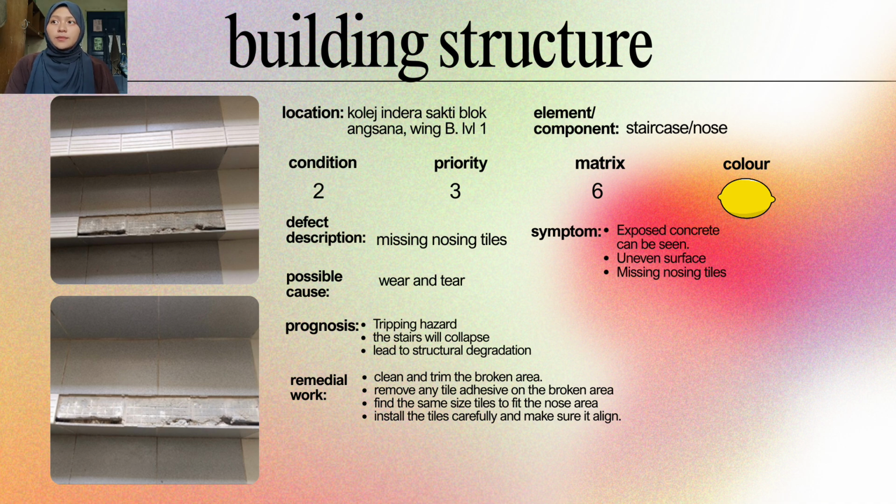Defect description is missing nosing tiles. Symptoms are exposed concrete can be seen, uneven surface, and missing nosing tiles. The possible cause of this defect is wear and tear. The prognosis of this defect will be tripping hazard. The stair will collapse, leading to structural degradation.